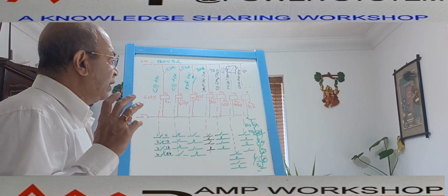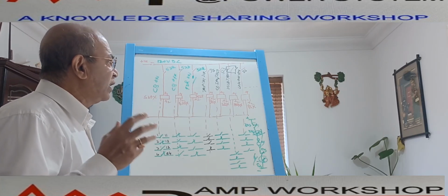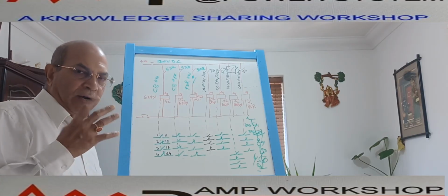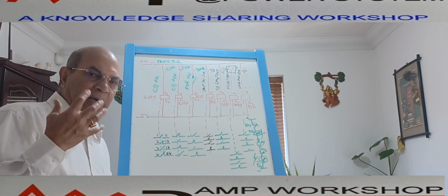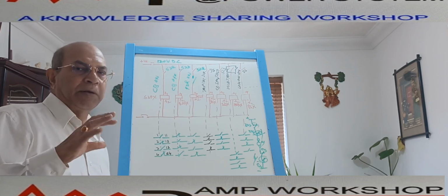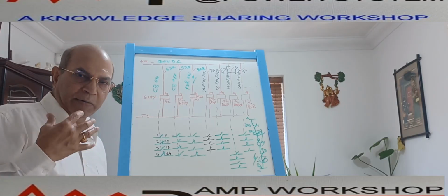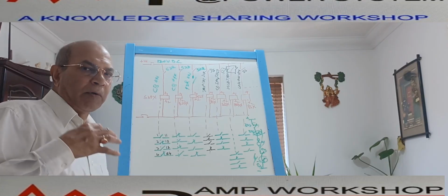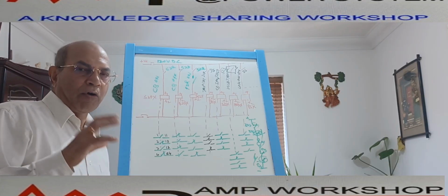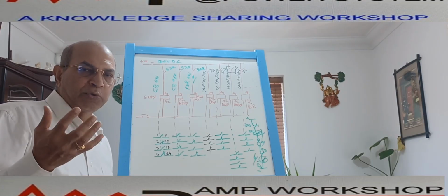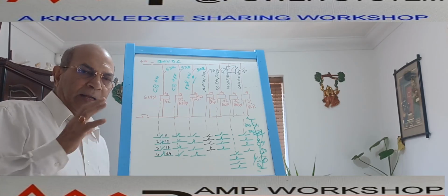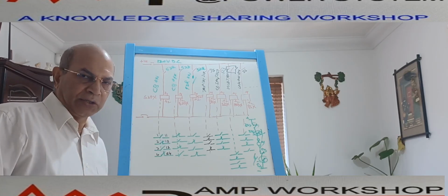Similarly, this circuit breaker has a spring mechanism. Then there is a lockout relay. We have seen the lockout relay; it has multiple output contacts available, but that is also limited, maybe 6 or 8 contacts. Some of the control switches, like the local-remote selector switch or the auto-close neutral trip switch, have different positions, and each has a contact that we use in various circuits.